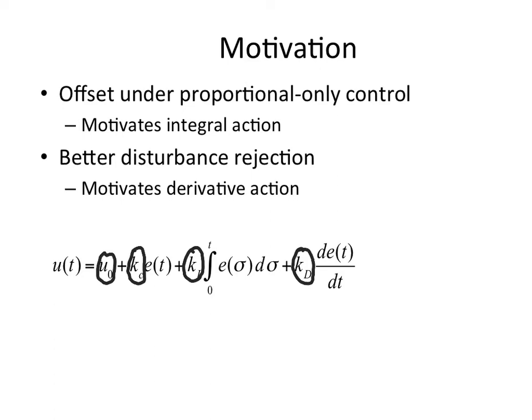Now, very often you'll see this written without the bias term because over time we can really think of this bias as being absorbed into the integral action. This form with the proportional gain, integral gain, and derivative gain is written differently on the next slide.